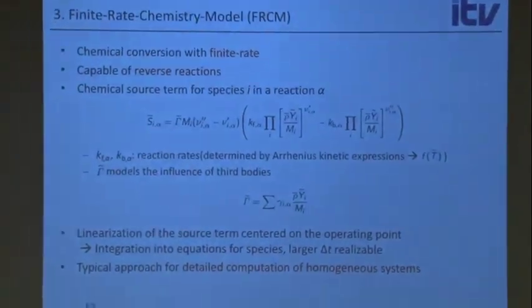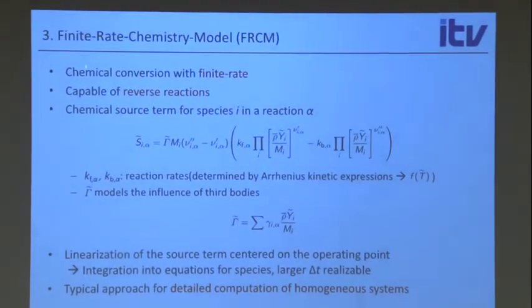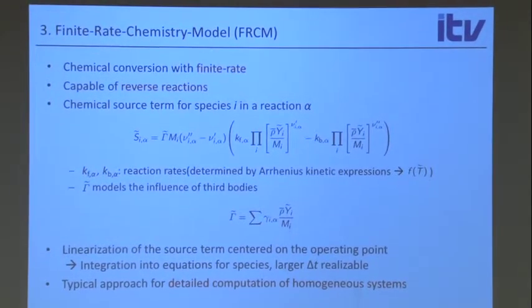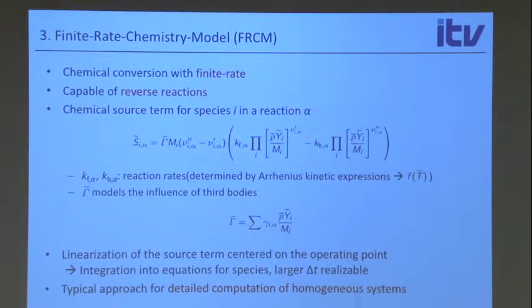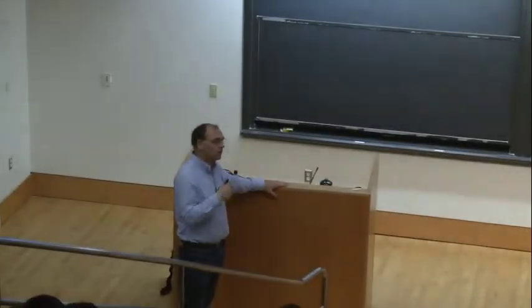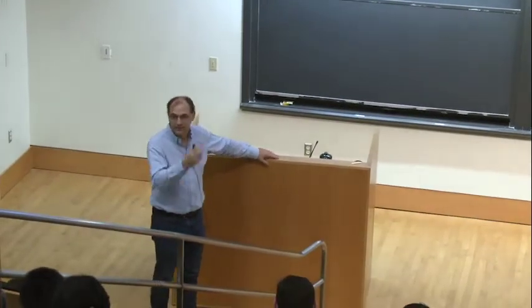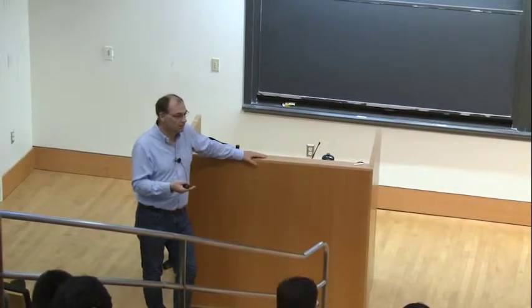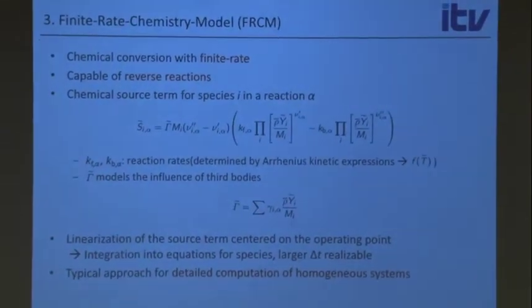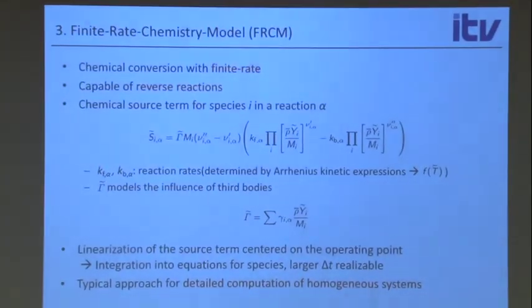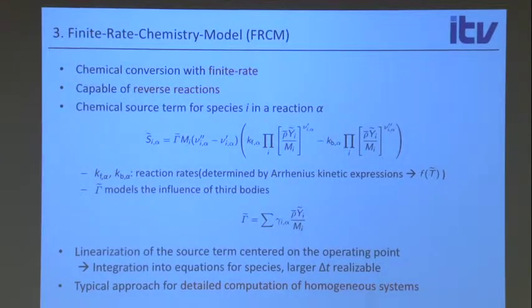So these are two classical models. Here's another model, called here number 3, the Finite-Rate-Chemistry model. And there are some other fancy names for this, but basically what the Finite-Rate-Chemistry model means is what I called no closure in the beginning. This is exactly evaluating the chemical source terms just with the mean quantities, which works well for very, very small Damköhler number, but it doesn't work for a normal flame or combustion case.